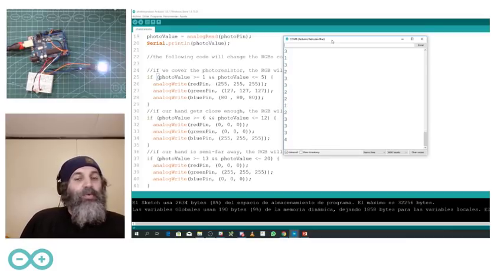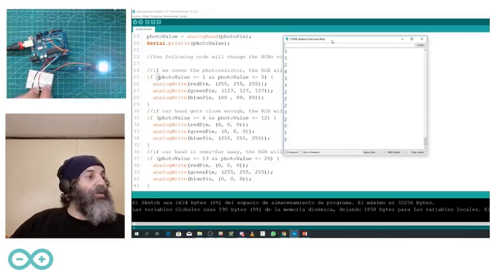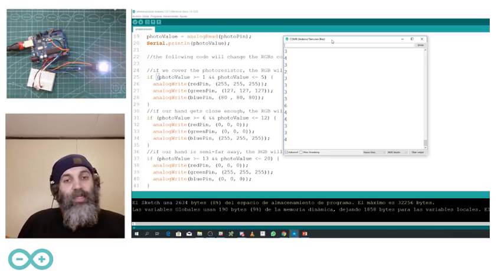When there is nothing on top of the sensor, I'm reading a value between 1 and 4. If I cover it, it goes down to 0, and you see. So probably what happens is that the light conditions are a lot better in my lab than they are at the place where Josephine and Carl were trying their program. So this is an issue, as I told you. It's very typical when you work with light sensing that the light conditions are very different in the different setups where you try things out.